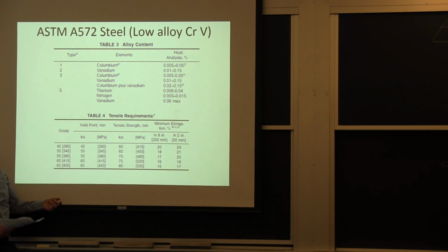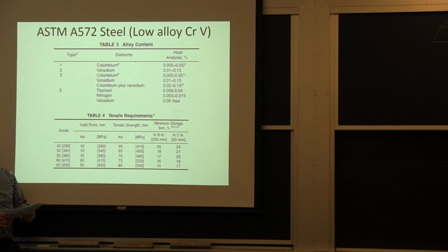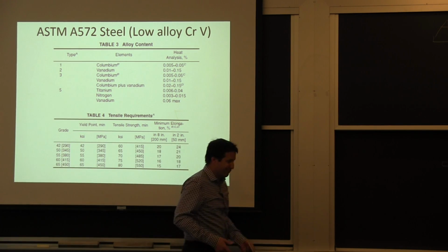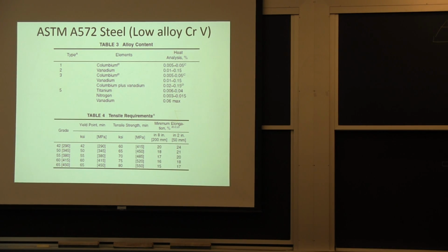So it's self-control, but in general terms, we call these performance-based specs, because I can go to the mill and pick my temperature, pick my drawing ratios, my rolling ratios. As long as I have the chemistry and I meet these mechanical requirements, I don't have big anomalies.